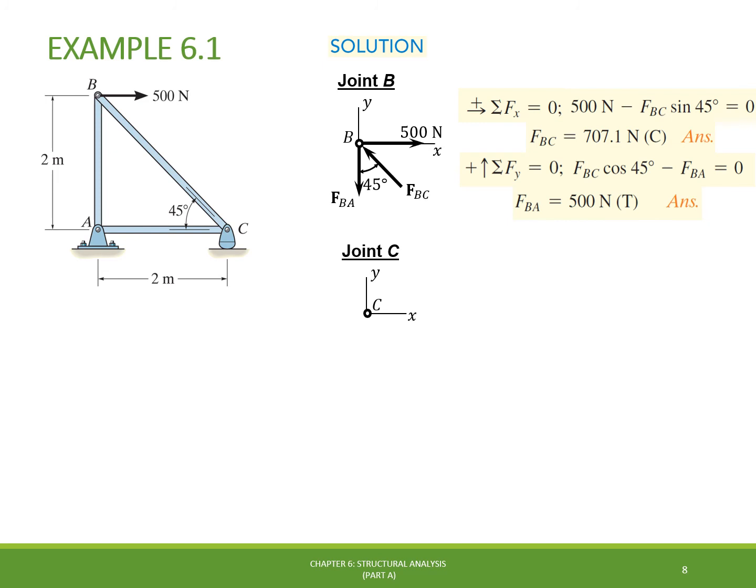By drawing the free body diagram for this node, we figure out that we have the reaction force Cy coming from the rocker support, which is naturally compressing the joint, and we have the compressive force FBC coming from the member BC. We know that FBC will compress the joint C because of the third assumption listed in slide number 4.